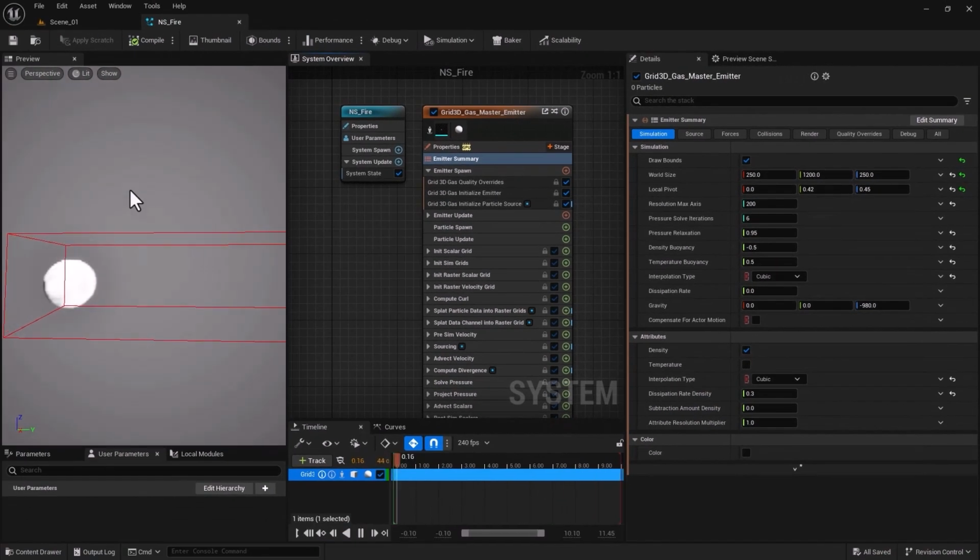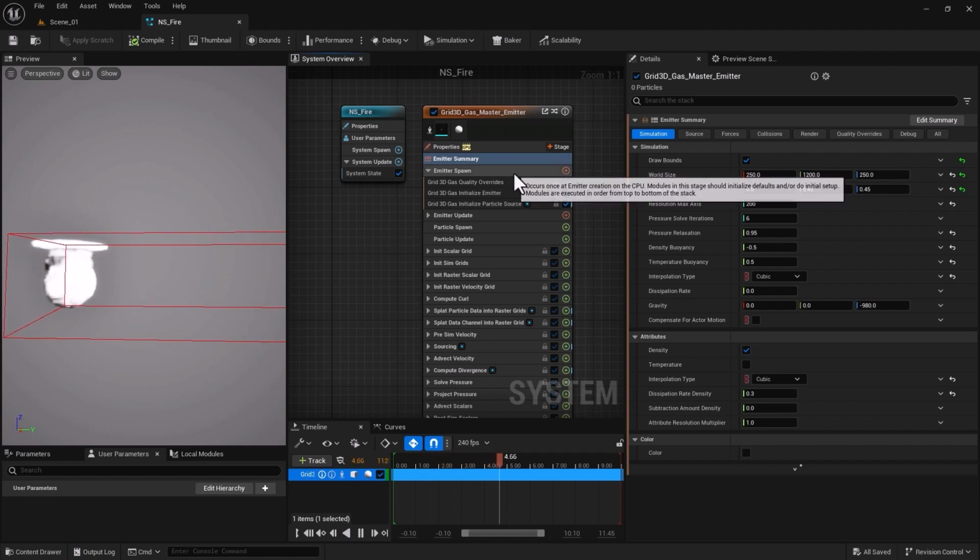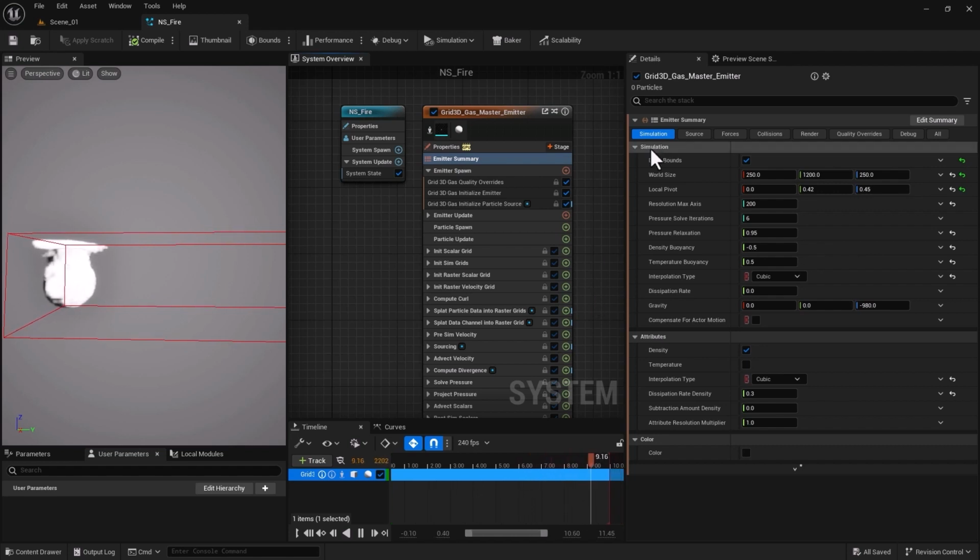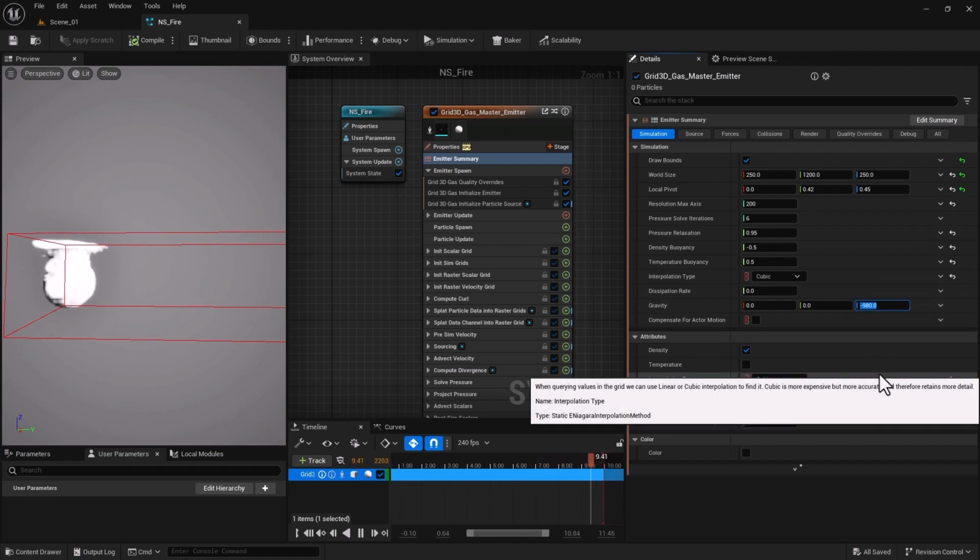All right, the direction of the smoke. The easiest way to get that going is by using the most powerful force inside the simulation tab. There are again many ways, such as velocity, to be able to push the smoke. My preferred method would be definitely gravity. So right now gravity forces the smoke to go up, and this is a standard gravity that you see in similar software packages. What I can do is to change that.